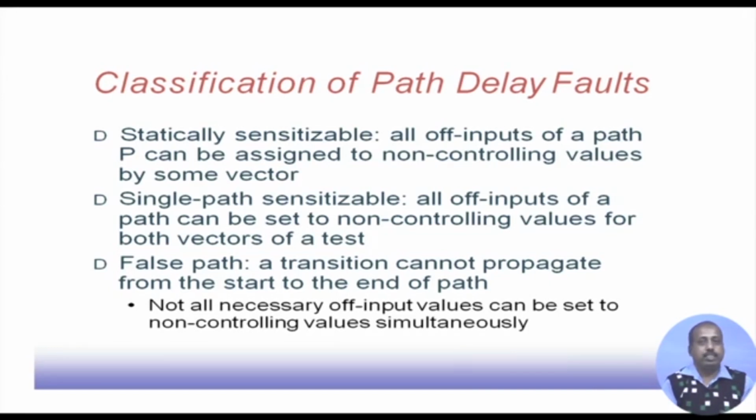So what it says is that apart from the path, all the inputs which are not affecting this path are off inputs of the path. So they can be set to some non-controlling value, so that they do not affect the propagation of this transition from the transition point to the output. So if we can do this, then such a path will be called statically sensitizable.